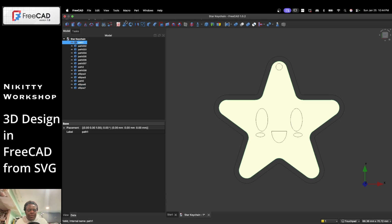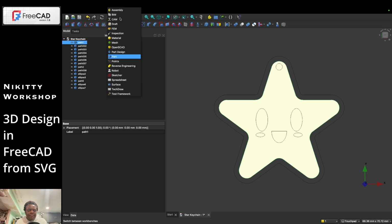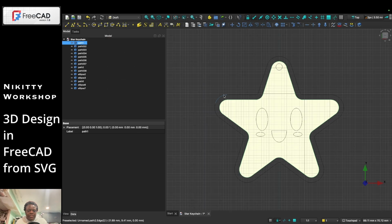So now we're going to go to Part. We're going to pick Draft. What happened now is we have to convert these paths into a sketch, and then we can extrude from the sketch out to the design or the 3D product. So this is the outside cheeks. I'm gonna start from the bottom because I think these from the bottom are the single ones.